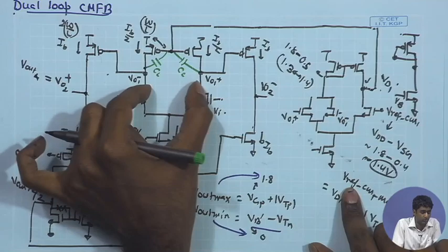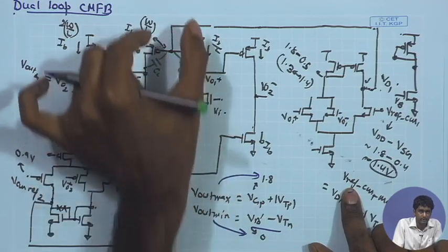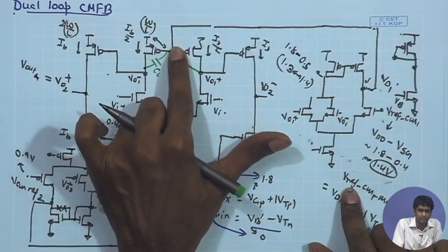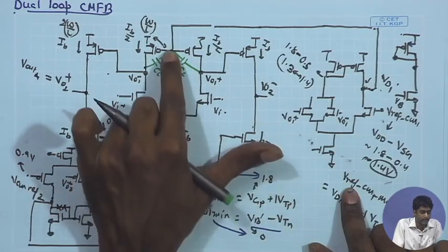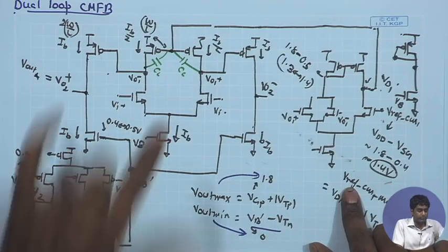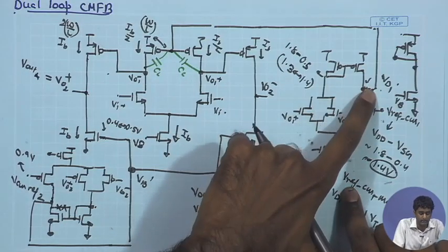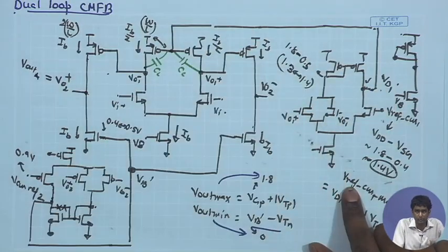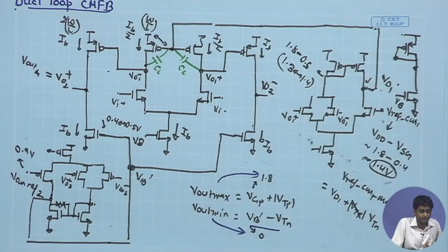In the equivalent common mode half circuit, remember, we tie these two drains together, gates together. So this becomes a common source amplifier with input as the PMOS device and the drain voltages as the output signal, and the CC also appears between the input and the output of this common source stage. Therefore, at this point you get a Miller multiplied capacitance, and that appears over here, and this is going to push the pole at the output of the error amplifier to low frequency.